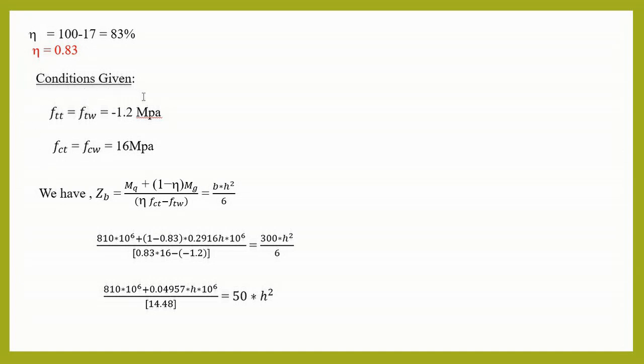Next are the conditions given. What does FTT mean? It is tension at transfer. FTW is tension at working load. FCT is compression at transfer. FCW is compression at working load.